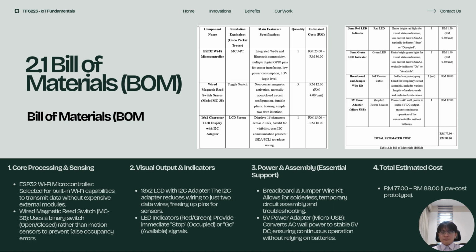Second, for the visual feedback, we use a 16x2 LCD display equipped with an I2C adapter. This adapter is crucial because it allows the screen to work using only two data wires, which frees up the microcontroller's pins for other sensors and LEDs. We also utilize standard red and green LEDs for immediate status indication.